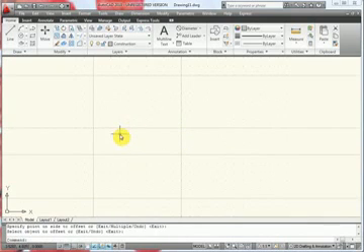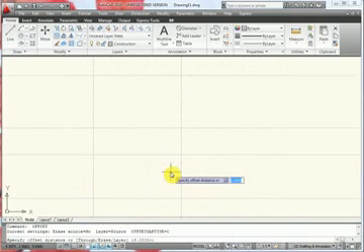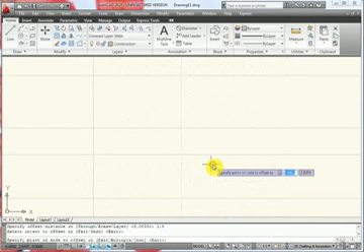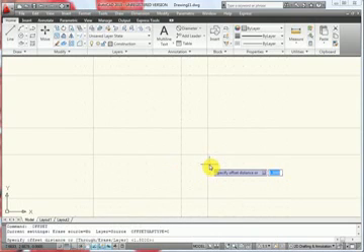Now I'm going to do all my vertical lines based after this 5-inch offset. So now I'm going to re-enter the command, do an offset of 1.5, and one more time an offset of 3 inches.